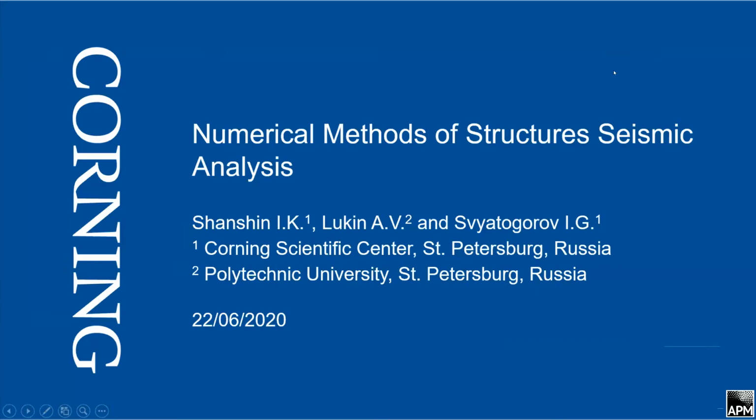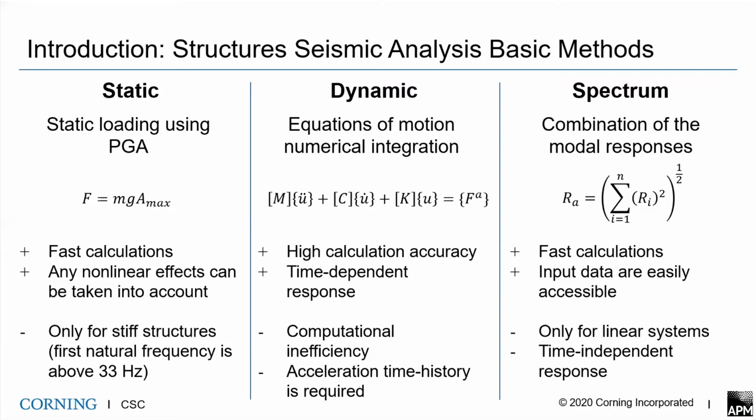Hello everyone again. Today I will show you my work about numerical methods of structural seismic analysis. So let's start with a short description of existing structural seismic analysis methods. The first and simplest one is the equivalent static method. This method uses only the maximum acceleration from an earthquake recording, which is applied to the structure as a static load.